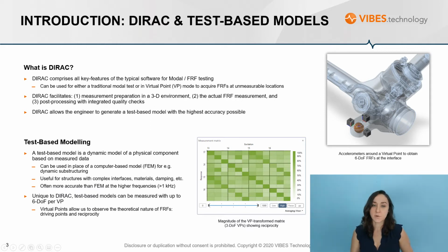However, we also might just want to use test-based modeling for a simpler component where we want to go to higher frequencies. Because I know some of you are really good at your finite element modeling, but when I tell you to go above 2 or 3 kilohertz, it's just going to be very difficult to get the accuracy you need for some of these activities. So that's where test-based modeling is really useful.